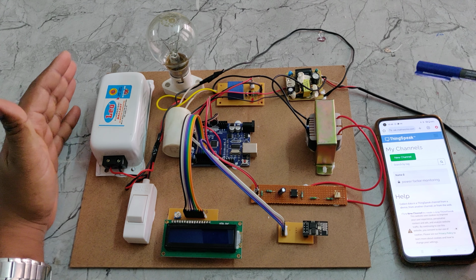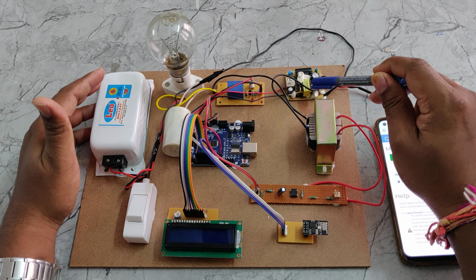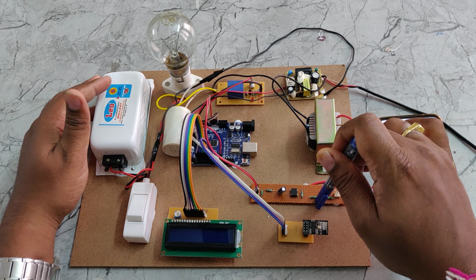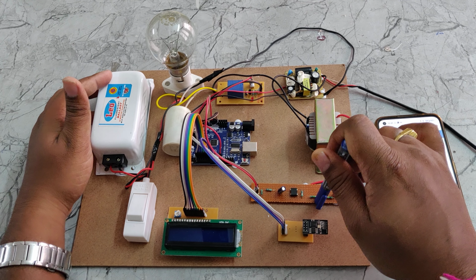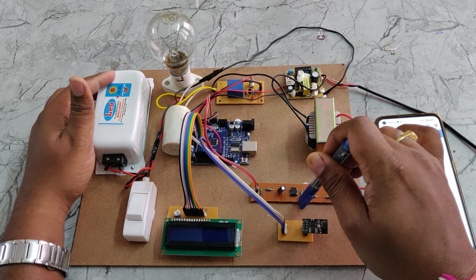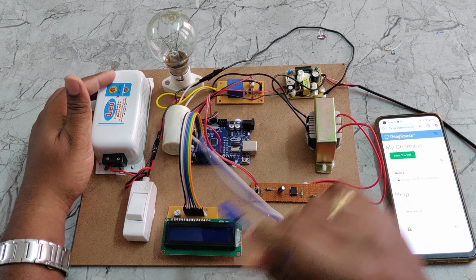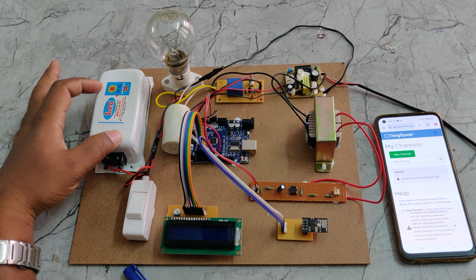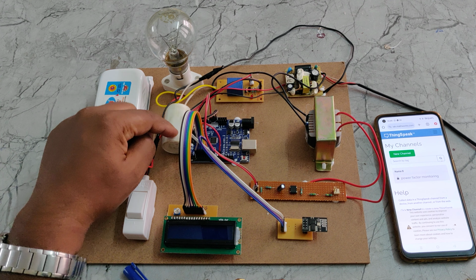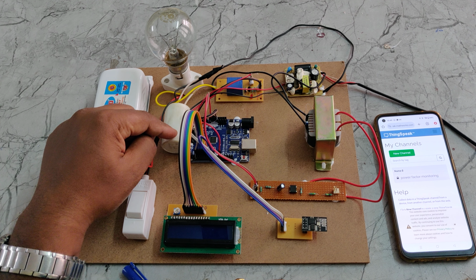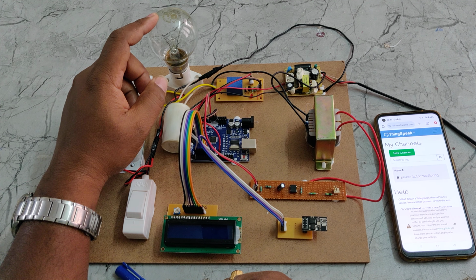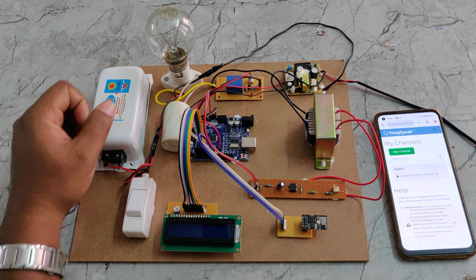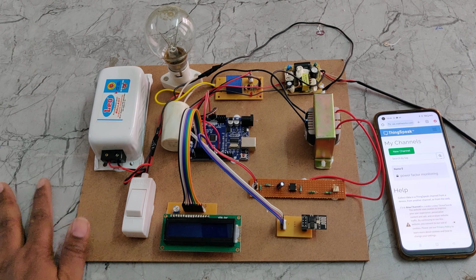The main components in our project are the voltage waveform sensor along with the RPS board and current transformer, to convert to low level voltages with the help of potential divider circuits, and the ESP8266 Wi-Fi module, the 16x2 LCD screen, and a mechanical switch, and an inductive load which is 40 watts, a capacitive load of 2.7 microfarad 450 volts, a resistive load of 100 watts, and an electromagnetic relay. And this is the main Arduino UNO board. So these are the major components in our project.